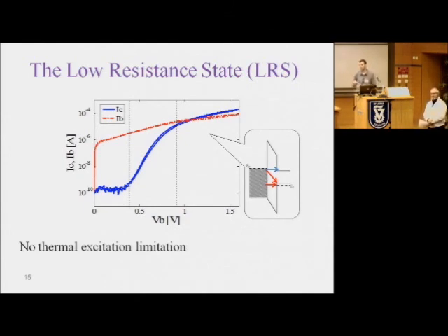Although it is a thin film, the base is very highly doped, and you can see here we didn't do much extraction, but probably in this voltage area we can extract the base resistance and tell the extra voltage drop after this voltage drop, like about 1 volt on the insulating film. When we increase the bias from here, the extra voltage drop could be on the base layer, because this is the limiting process here.